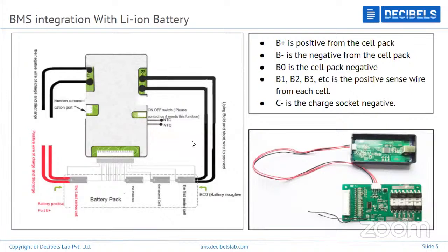Why is it? Let us assume that you have a 60 amp BMS. If you want to select a wire which would allow for 60 amps, it would be very thick. So what I will do is use two wires of 30 amps, which will just add up. I'm just dividing the current into two, so that the thickness won't be more, and it's also safer.